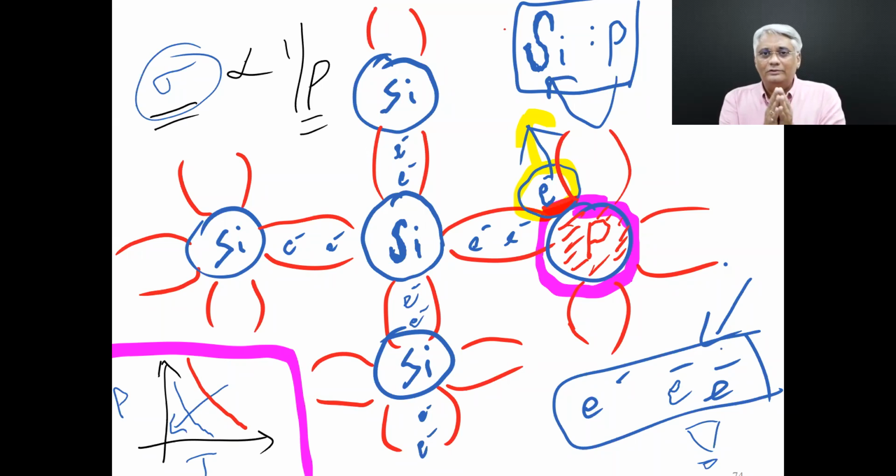So in a semiconductor, you have mobilities coming from electrons as well as holes. Mobility from electrons, mobility of holes. Total conductivity is conductivity from electrons and holes. So when you make it into an electron-based semiconductor by phosphorus doping in silicon, the majority carriers are electrons.